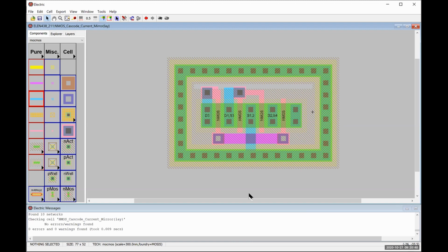So we have a situation here where effectively our electron mobility in our NMOS transistors is 3 times as large as our hole mobility in our PMOS transistors. It's actually closer to 2.5, but we'll just call it 3 for now because that's what the book uses. So we're going to size this PMOS transistor. Instead of being 10 by 2, it'll be 30 by 2.